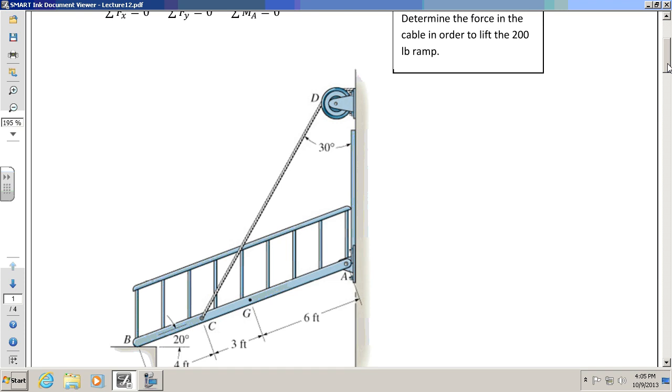So I'm thinking I probably need to draw a free-body diagram of the ramp. Now, there's really no need to draw the handrail and the connection between the handrail and the ramp. I think this is a sufficient drawing, something like that, okay, where this end point is point B and the other point is point A, like that. You don't need to draw a thickness to that or anything else like that. Notice the line from B to A. All the forces are pretty much on a line between B and A. There's nothing really relevant about the handrail or anything like that.